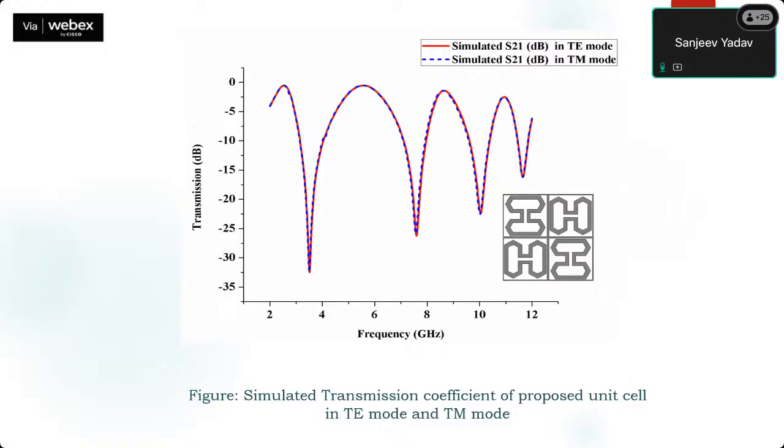It's simple. I just want to ask about a simple antenna that is connected orthogonally. We are putting the decoupler between them to reduce the mutual coupling. Then how do you design the electrical equivalent circuit? You need to use a capacitive element in between. Only a capacitive element? Yeah, but for the mutual inductance, a little bit of L can also be used.